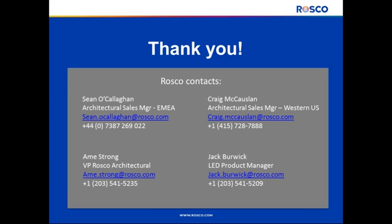Okay, good stuff. One on controls again and types of power, referring to the fact that there's different types: constant current, constant voltage for LED tape. What can RoscoLED use, can it use both, or what's preferred? The primary or preferred control method is the constant voltage. So again, in the architectural world, I know 0 to 10 volt is very popular. So certainly it's very easy to control all the static whites using 0 to 10 volt. It can also be done with the colored tape, the Varicolor, or the tunable white. It just requires some additional control slides to do that.